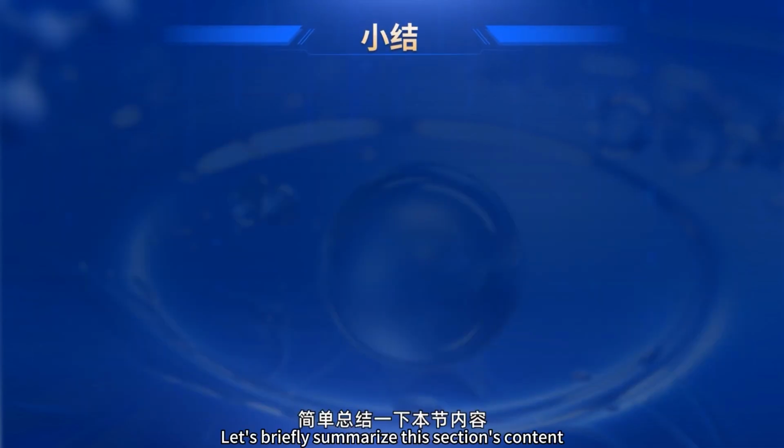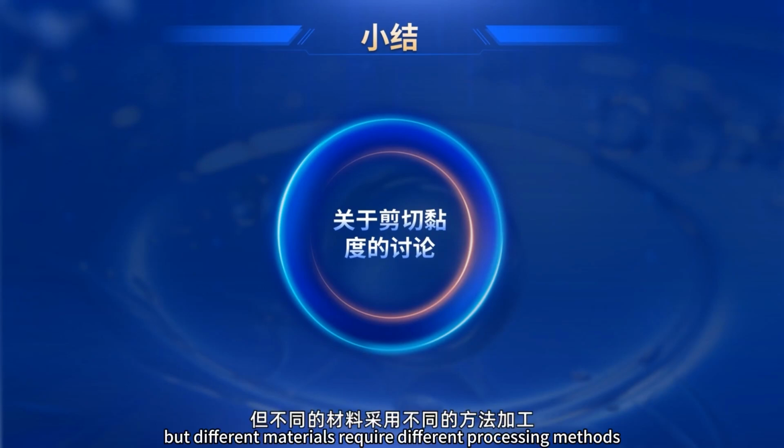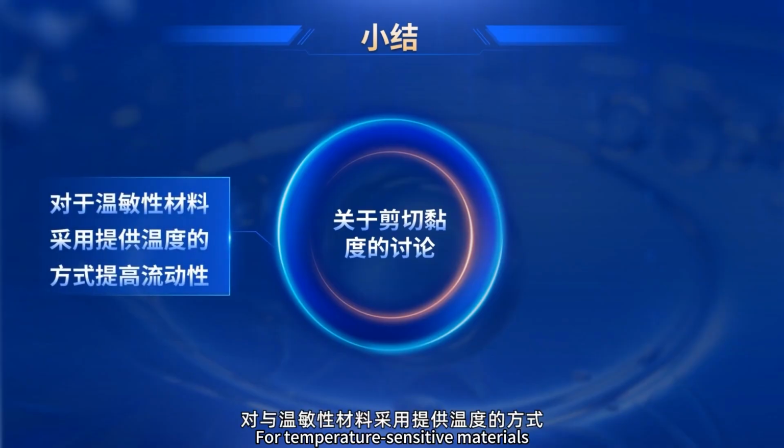Let's briefly summarize this section's content. Both increasing temperature and pressure can reduce a material's viscosity, but different materials require different processing methods. For temperature-sensitive materials, raising the temperature is used to improve fluidity. For shear-sensitive materials, increasing the shear rate is the method to enhance fluidity.